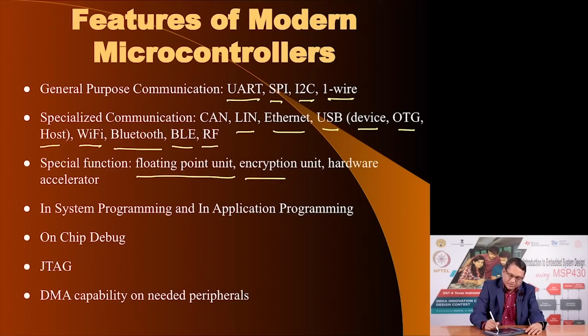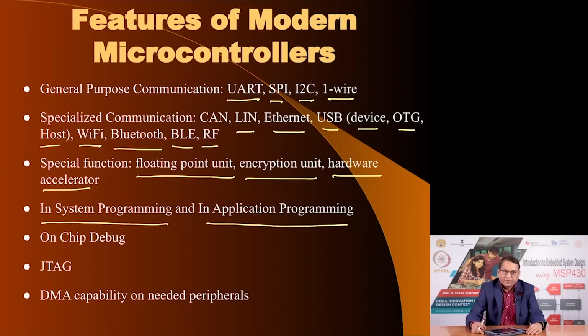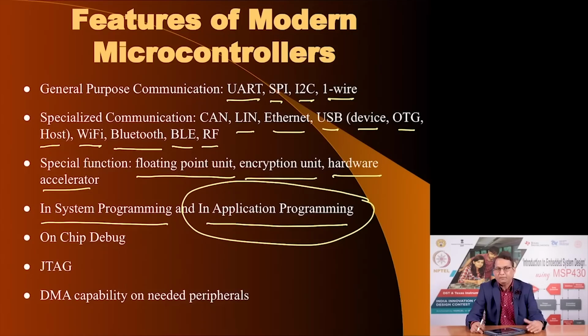They may also offer encryption units to encrypt the data before you save them, and these are called hardware accelerators. There may be hardware accelerators for other activities. Most modern microcontrollers will offer in-system programming, and some of them may also offer in-application programming. Our MSP430 that we are going to use offers both these modes, and in fact our kit operates through the in-application programming mode. We will be able to upload a program while the system is still on, and so this is one of the modes of programming the microcontrollers.